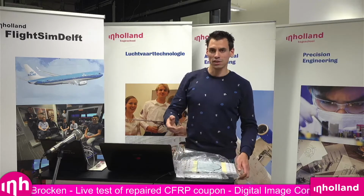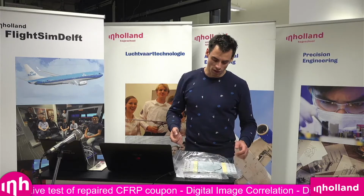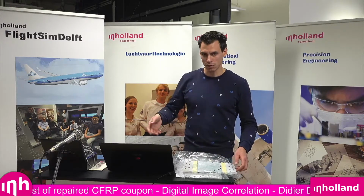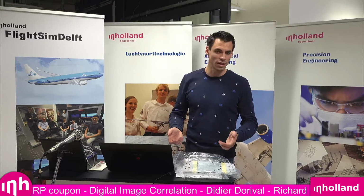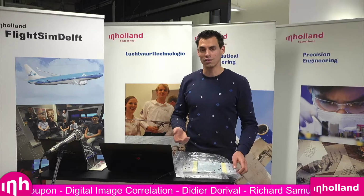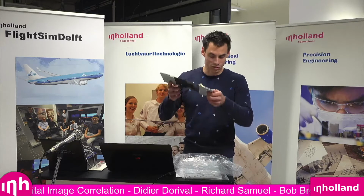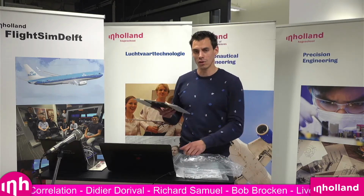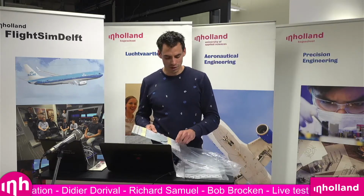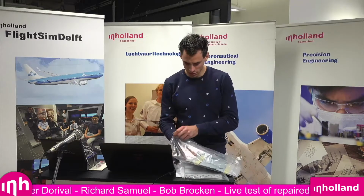And you can also imagine that if you have this on your aircraft or on any structural part, which might be prone to being damaged by someone dropping something on it, if your zero layer is the outer layer, this is the layer which gets damaged the most, which might result in catastrophic failures such as these. So that is generally why it's good to put your zero layer not directly on the outside. You have to be careful with the splinters here.